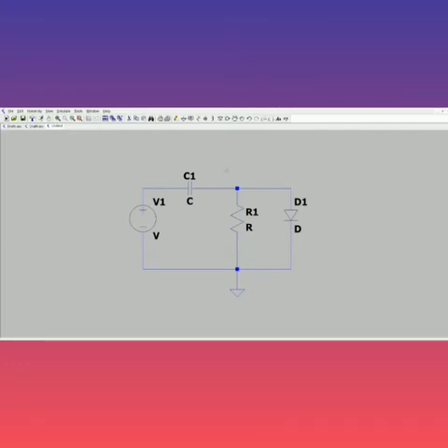Now I have to name the components. So I'm naming my capacitor to be 0.1 microfarad. So for micro, in your keyboard, just put U. So it assumes that it is a micro. So give OK. Can you see this? It is changed to 0.1 microfarad. Now I'm giving a resistor value as 1 mega ohm. So type 1 MEG like that. Don't put only M, so that it assigns like it is a milli value. So put 1 MEG, give OK.